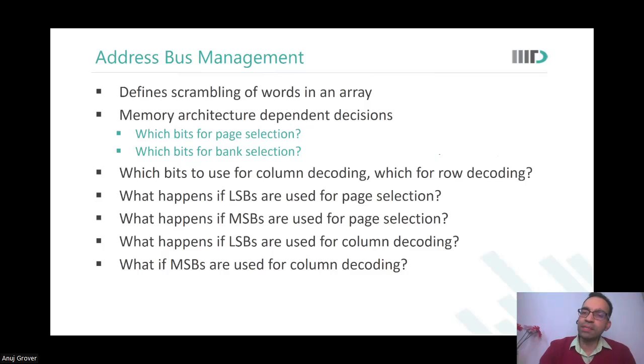Yeah, let us simply say, Abhi, if I want to say word 0, word 1, word 2, word 3, right next to each other in a given row, which address bits will you send to the column mux? Which address bits will you send to the column mux for decoding this? 0, 1, 2, 3. The LSBs, address 0 and address 1.